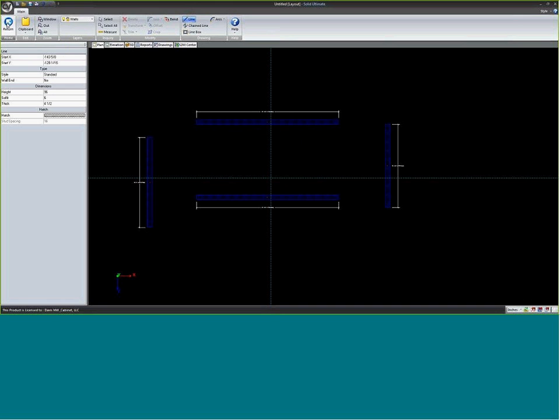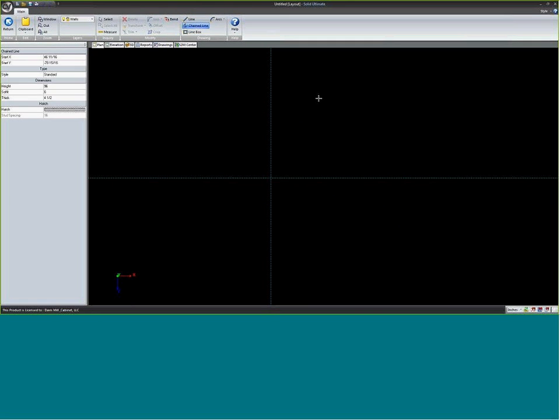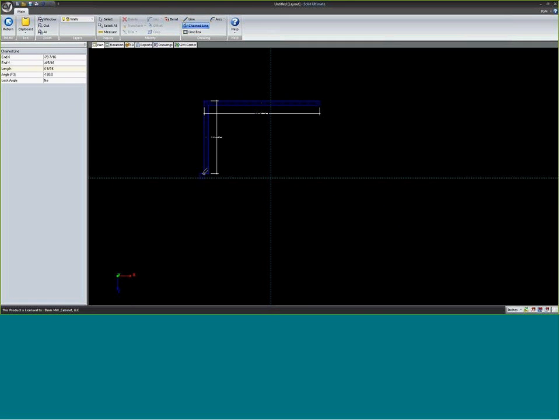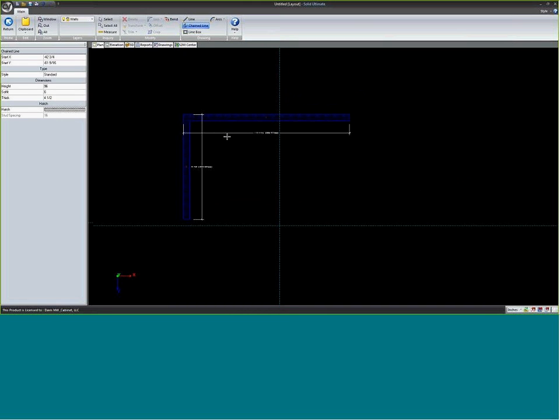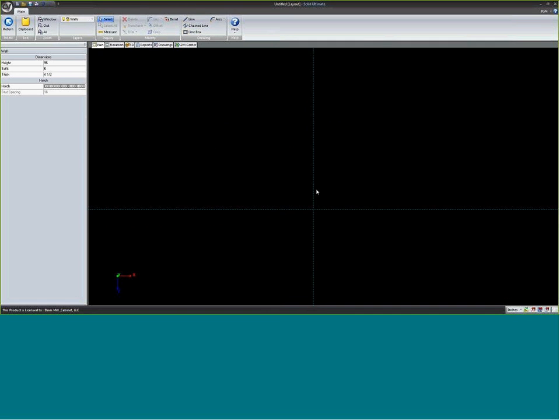If you draw backwards, it's not the end of the world. The problem will be confusion in cabinet dimensioning, because all of the automatic dimensioning will come out in front of your cabinets that are attached to these walls. So it's just always best to go clockwise around the room. A couple of pointers on laying out rooms.